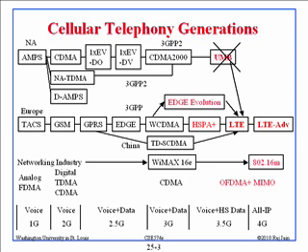Okay, so this line I have shown here, actually this line should have come from EDGE. That line is misrepresented there. But what it is showing is that the GSM guys have a choice, or at least planned, to go from EDGE to WCDMA. However, this is a total change. Why is it a total change? Because this is TDMA and this is CDMA.